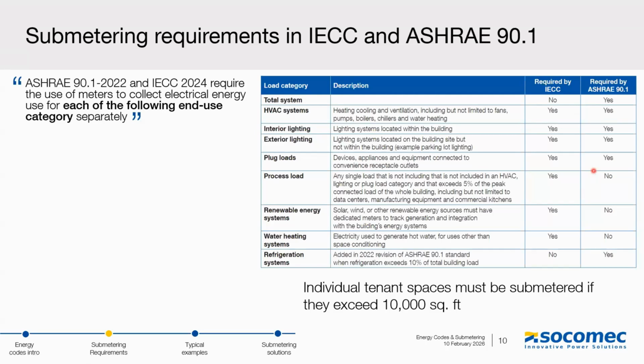As for the other ones, there's a few minor differences. For example, ASHRAE is not requiring to monitor process loads. Same thing with renewable energy systems and water heating systems, but they do require refrigeration systems where IECC is not requiring that. So those are the different load categories that the standards are asking to monitor individually.